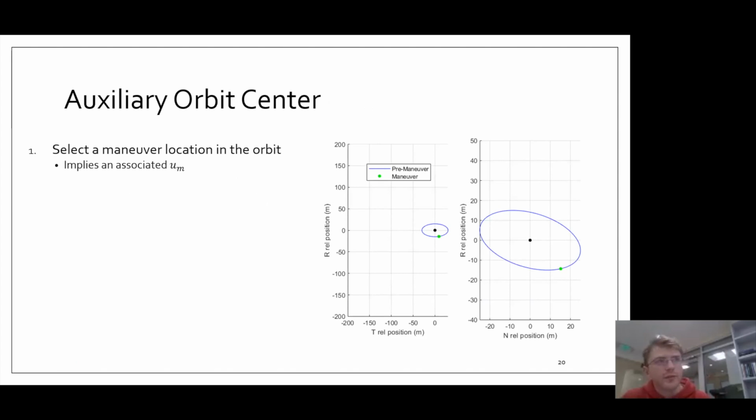We discover some kind of fault, we predict some kind of collision, we decide we need to maneuver. From this point, we decide we need some relative semi-major axis. So this, I think, would be well designed as part of the mission requirements in the planning phase, on what sort of relative semi-major axis you'd want to expect from your spacecraft formation if it needed to go into this recovery mode.